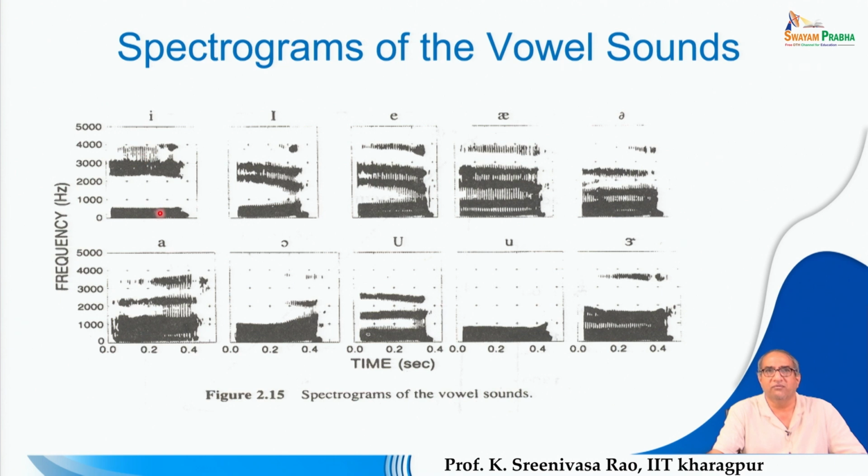And this is the spectrogram for E. You can see there is low frequency content, as we have seen, and then very high frequency content. In between you do not see any other frequencies; there may be frequencies, but they have very insignificant energy. So if you want to discriminate the vowel E from the rest, you can clearly say that the difference between F1 and F2 is very high in the case of vowel E compared to the other vowels.